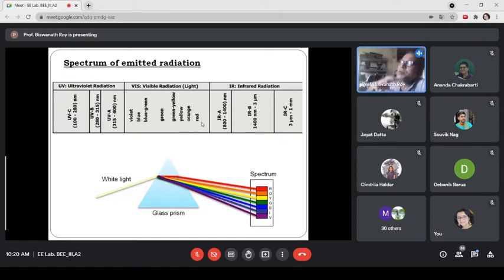So the efficiency of converting electrical energy to light is measured with the output of the electric lamp, which is measured as luminous flux, that is lumen, and the input power is the electrical power, that is watt. So luminous flux in lumen and electrical power in watt. So lumen per watt. This is the measure of energy conversion efficiency of an electric lamp, right?